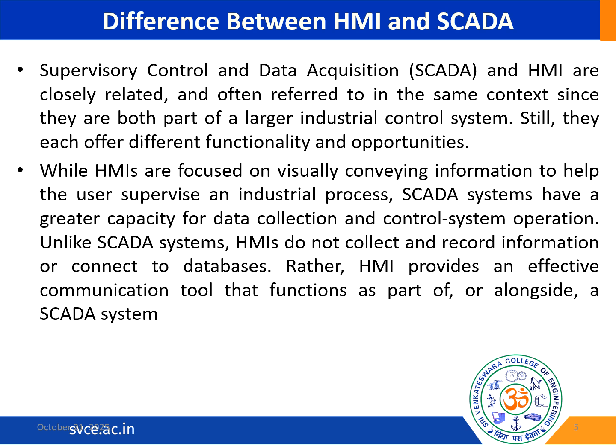When you compare it with SCADA, on the other hand, it encompasses a broader scope. It not only interfaces with HMI but also handles data acquisition. It can also be used in historical logging, remote control, and it can integrate with databases and the enterprise systems.